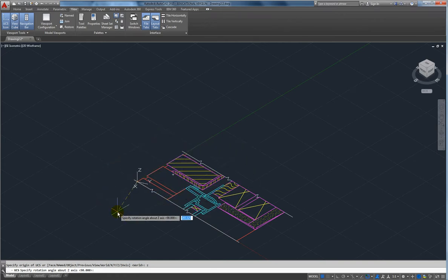And say for some reason I want to rotate 180 degrees. So all my rotations are based on degrees, not radians, luckily. So it's based on degrees, so we can go 0 to 360. The great thing about AutoCAD is they try to be really intuitive, and they make counterclockwise positive. Counterclockwise are positive. They're not being intuitive. That's all. So all my rotation happens counterclockwise in AutoCAD by default